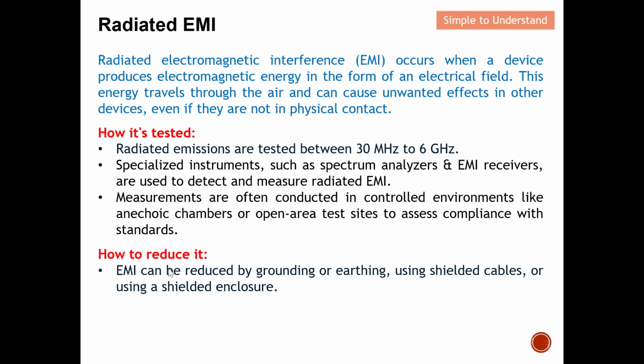How do we reduce this emission? EMI can be reduced by grounding or earthing. If not, you can also consider using shielded cable or building a shield to enclose the noise source. So this is for radiated EMI.